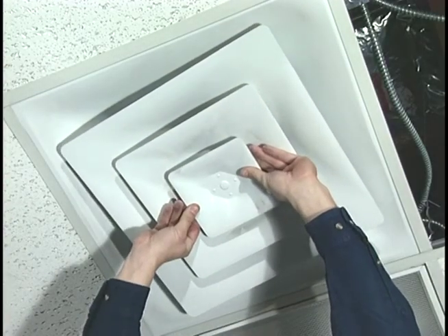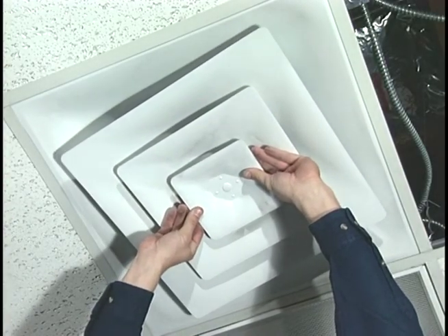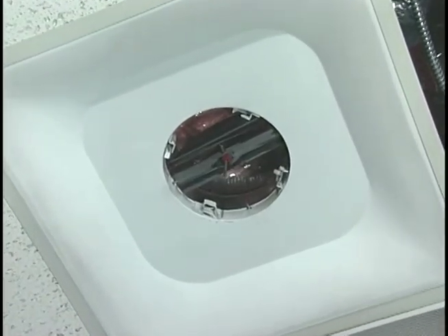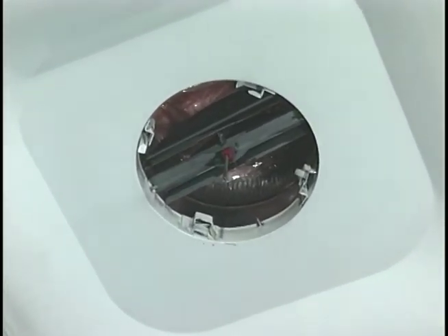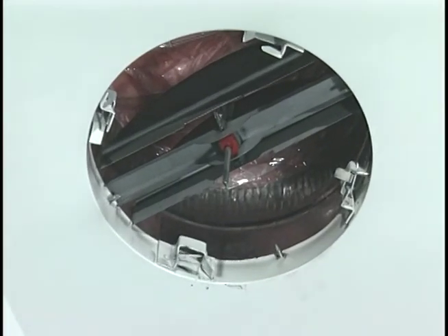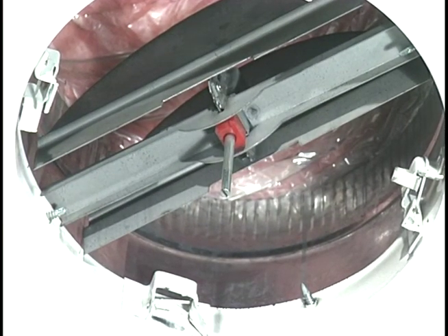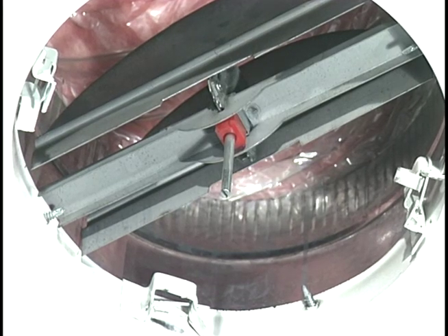The experienced technician will not use the outlet or inlet device's face volume damper to reduce airflow. Using a register's or ceiling diffuser's face volume dampers to reduce airflow can result in excessive noise, poor air distribution, and an improper balance.